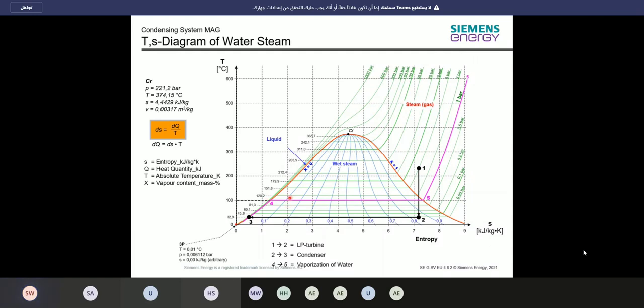Temperature is constant. So when you're getting in here, you still have 100 degrees. And you have water at 100 degrees, and at the same point, you have an amount of steam with 100 degrees. And at this point, you have around 10% steam already in. So 90% water at 100 degrees, 10% steam at 100 degrees. The temperature is equal. You're not going here somehow saying, oh, evaporation is starting and it's going down to 70 degrees and then going up again.